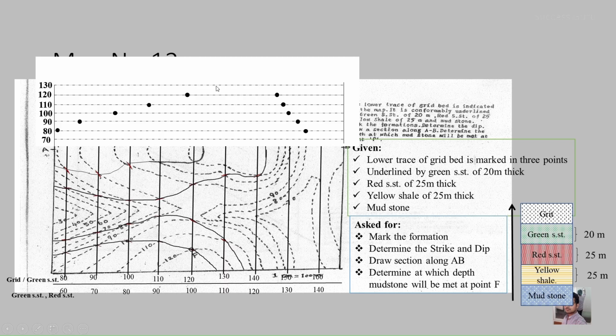If you touch the line at this point, it simply means you have a 130 contour, but actually it is not there, so you have to keep the profile line below this line. Like this you move to 120 here, then 110, 100, 90, 80, and we don't have a 70 meter contour in this place, so you have to end this line above 70, in this region. So let us try that. This is how the profile line is.